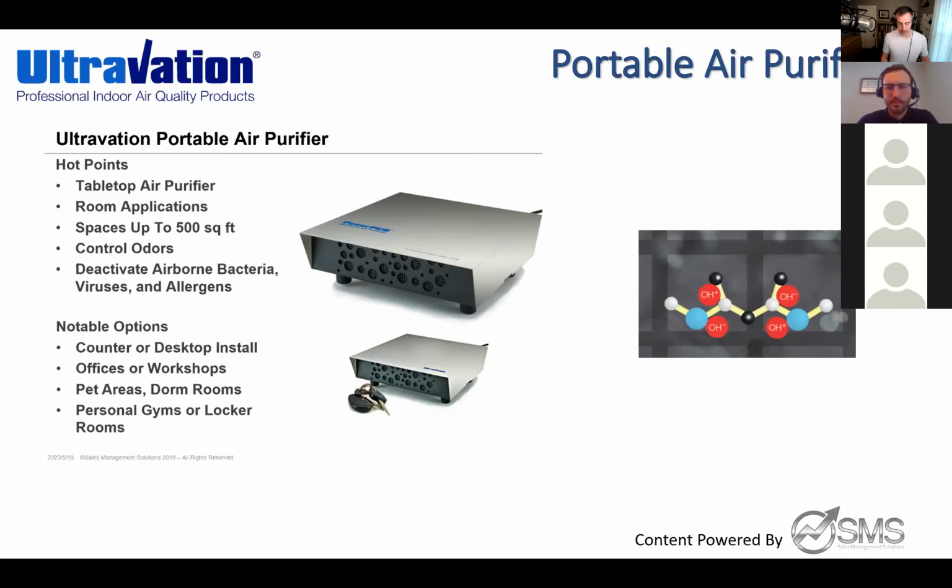Now, is that like a throwaway product? Is it serviceable, or what's the longevity of it? Unless your air's really dirty, you just open it up once a year. You can take the little filter out, just wash it off, and then you just change the bulbs once a year. So it's an annual PM, so to speak. But no, that's not a throwaway unit. That's something you leave there, just come back, wash the filter, change the bulb.